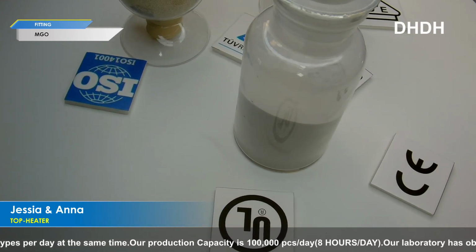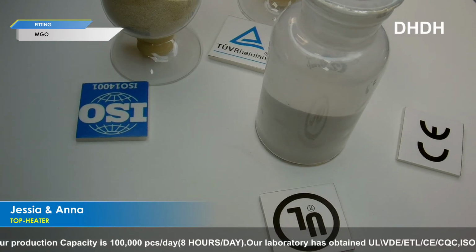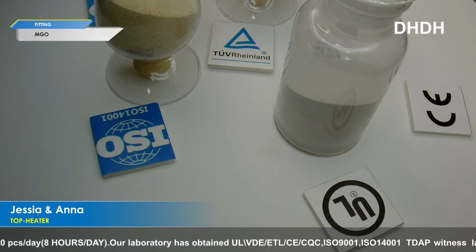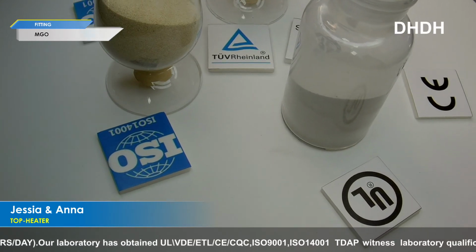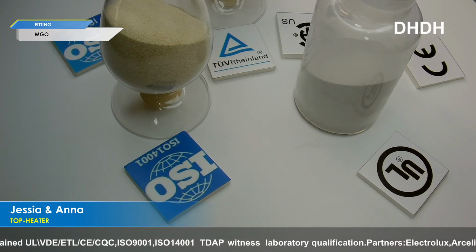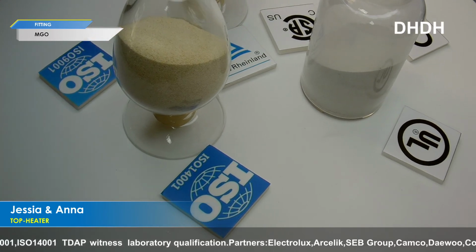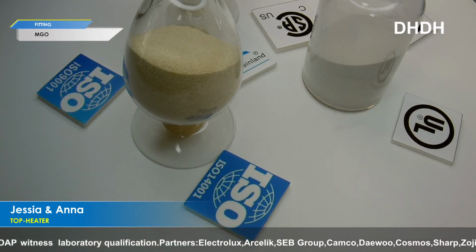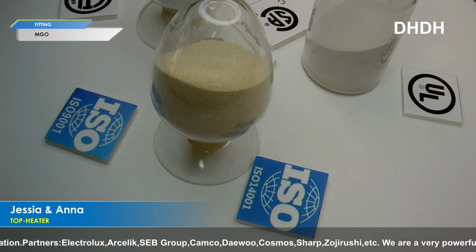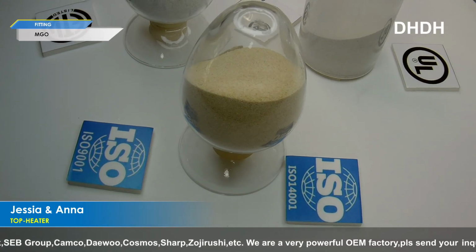The second is about the working environment. If your heaters are air heat or liquid heat, the MGO powder will be different. Some, like convection heaters such as irons and rice cooker heaters, need a different model. So just tell us which appliance and which heating elements your MGO powder is used for, and we will consider it and make suggestions.